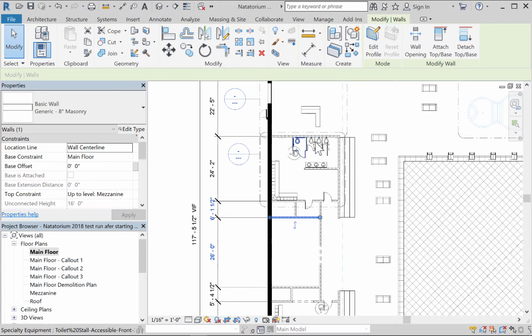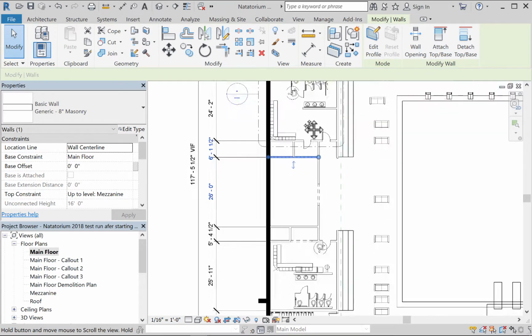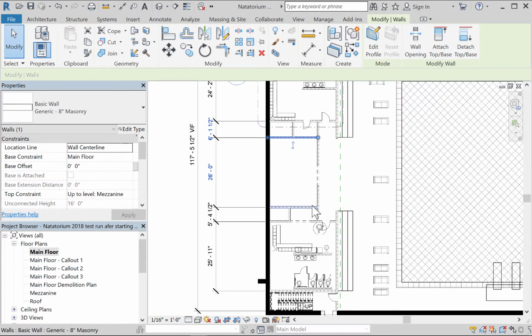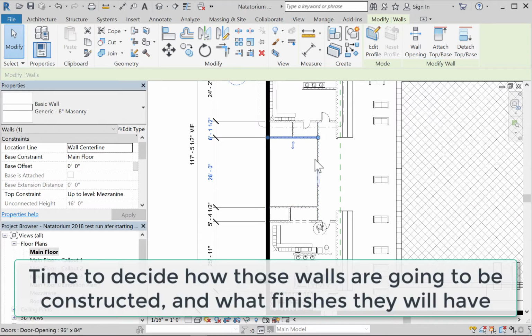So, for example, toilet rooms are kind of noisy. There's a lot of flushing. There's a lot of air dryers. They're kind of annoying. So, I think I'm going to go with concrete block construction, because it's waterproof. But on the outside, I think I may want to put some acoustical abatement on there, just so it's a little nicer. Okay. And then just for the heck of it, for the other walls around the snack shop here, I'm going to make these out of drywall.